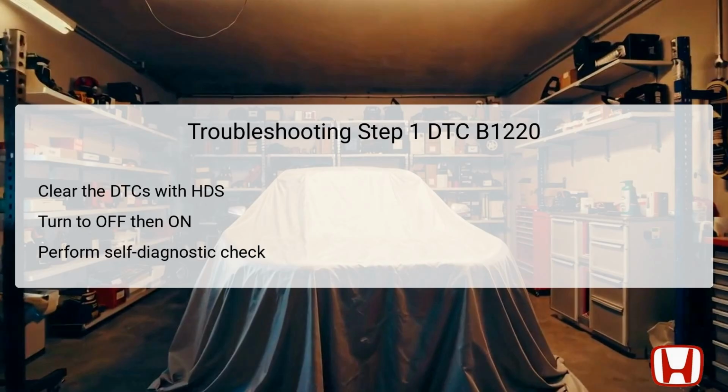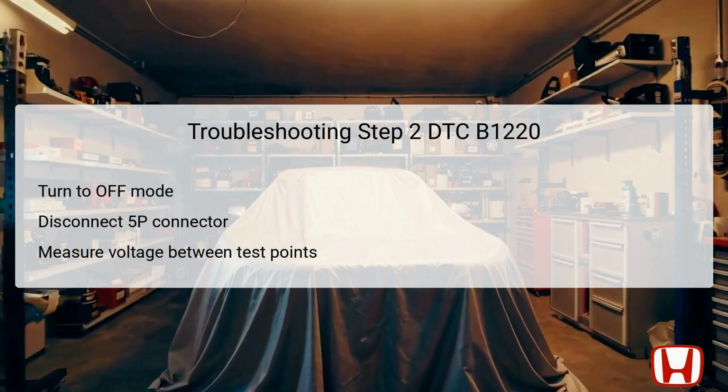If DTC B1220 is indicated, further diagnostic steps will need to be performed, whereas the absence of the code may suggest an intermittent fault requiring visual inspections of wiring and connections. Step 2 of the troubleshooting process involves narrowing down the possible failure areas. Start by turning the vehicle to the off lock mode to safely work with the electrical system.